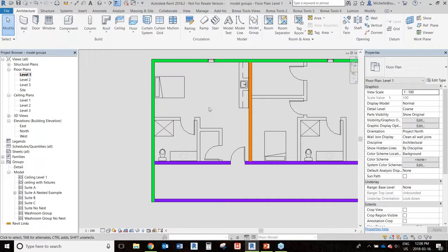And it might just limit how you have to organize your groups. Now, instead of having the option to not include your walls, you kind of get directed down a path where you have to have them because all your content's been set up that way. So I really like to prefer having most of the content not hosted where possible. Obvious examples, you need to have things like windows and doors, but anything else, try to limit that as much as possible.